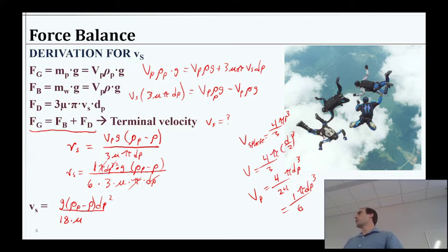I'm giving you this equation on the exams, but in large part the point of going through this with you here is so that you have a better understanding, I hope, of what's going into the sedimentation velocity. Because think about what happens if we change the particle size versus what happens if we change the gravity? Let's say we try to do it on the moon, right? Or what happens if the water becomes more viscous? What happens if you try to do this in honey? What about ethanol? It just happens to be less viscous than water, right?